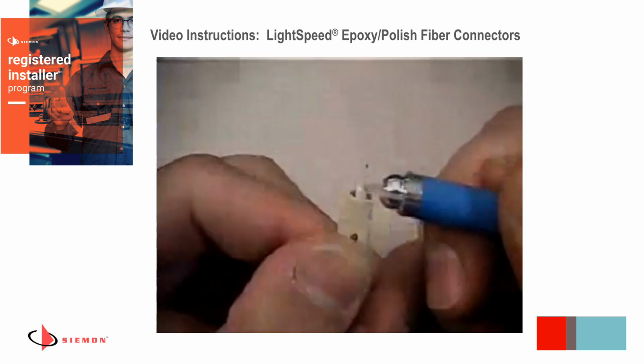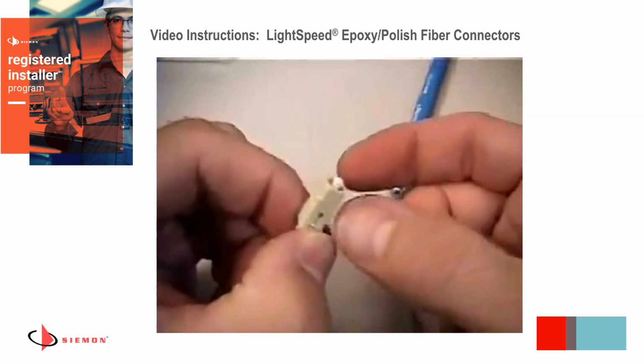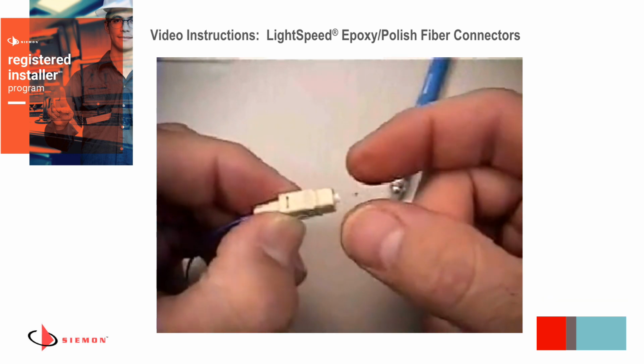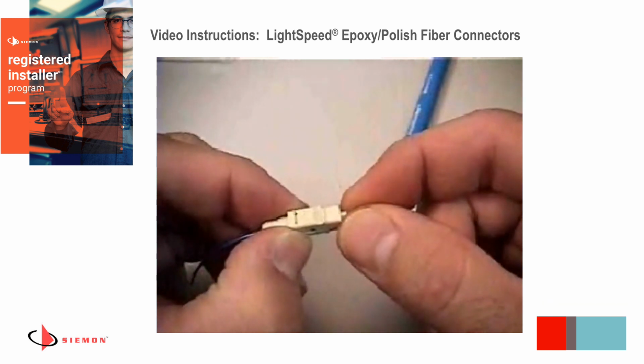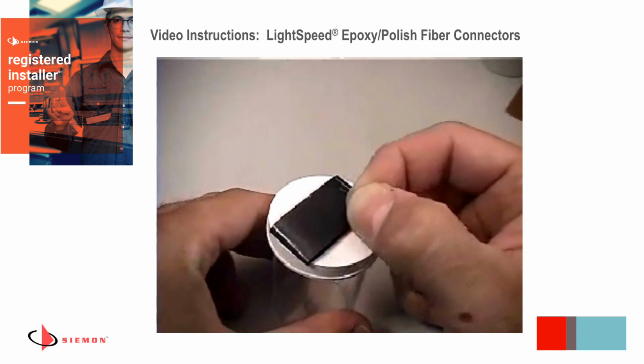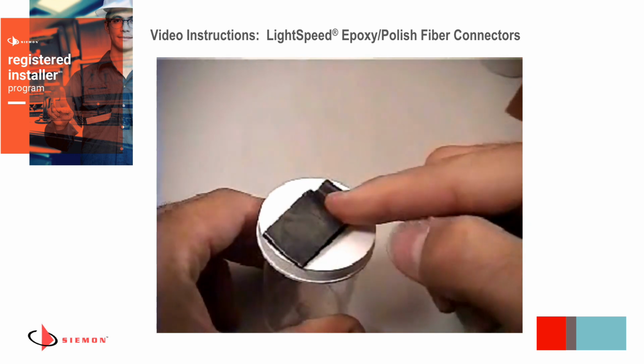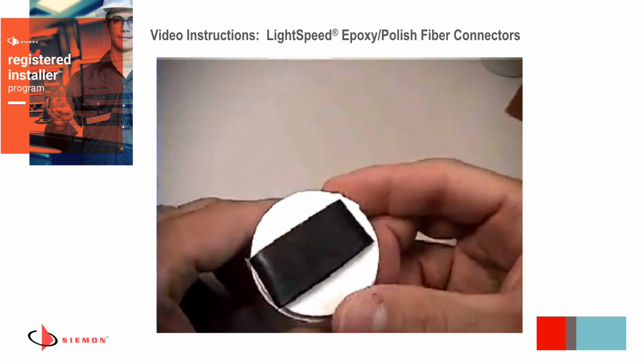If properly scored, the excess fiber can be removed with a straight, non-twisting pull. Deposit the fiber piece in a safe place, such as onto a piece of electrical tape or into the debris container included. If the fiber does not readily pull off, repeat the previous step, scoring on the opposite side of the fiber.